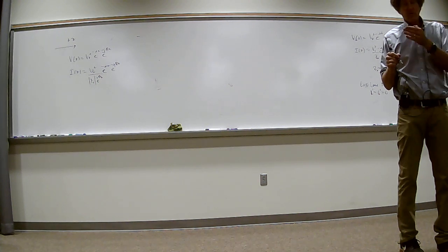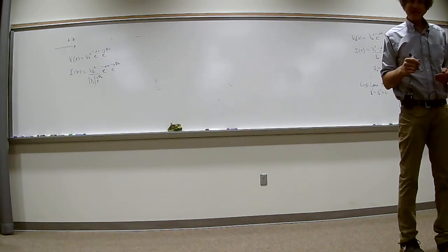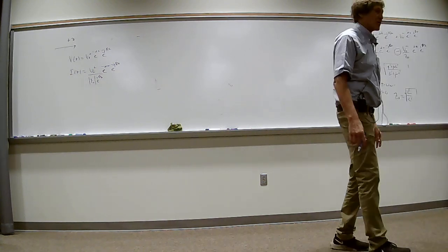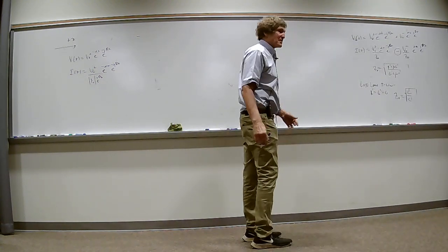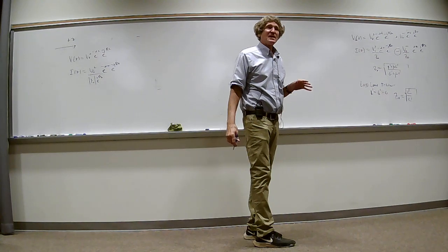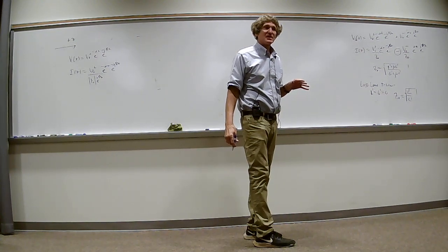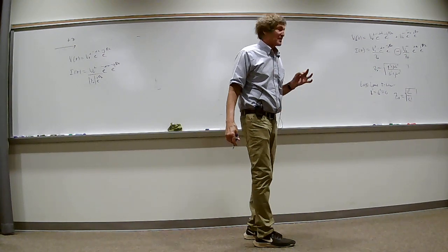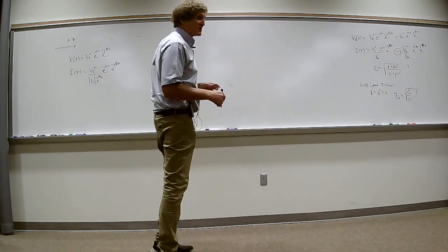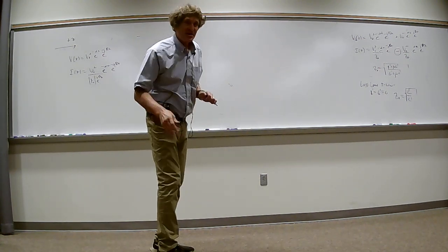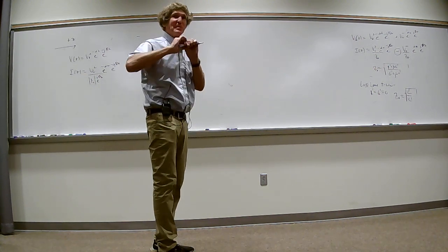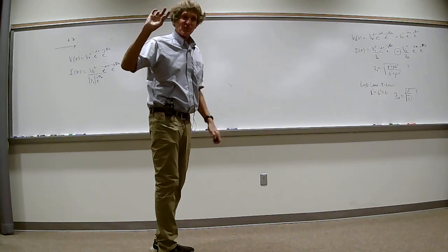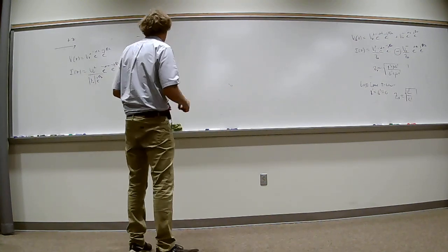So you're an electrical engineer. You should at least experience what you're probably going to see all the time in the real world. Go take a look at it, see if it is 75 ohm. Is there anybody aware of any other value for what's coming off the street? I think it's always 75. Pretty sure. Anyway, that's what they mean by this. The ratio of L and C, by the way, has nothing to do with the inherent resistance per meter of the stuff, as some people mistakenly think. It is actually the square root of L over C.